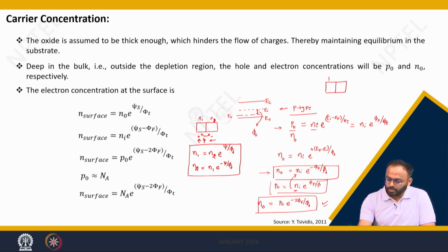You know that if it is P, it is N. Majority and minority concentration in P-type and N-type can be represented as Pp, then Np. Similarly, this can be written as Nn and Pn. So you can write a junction law to relate these quantities, Pp and Pn and all, meaning how the minority carrier can be written in terms of majority carrier and vice versa.